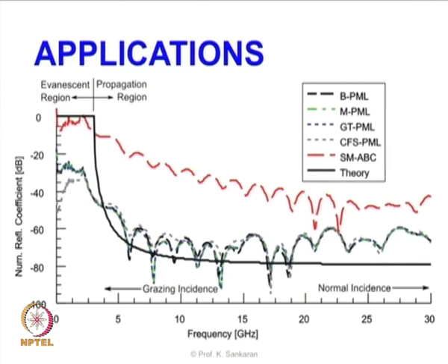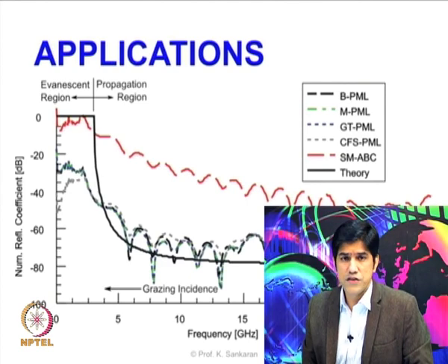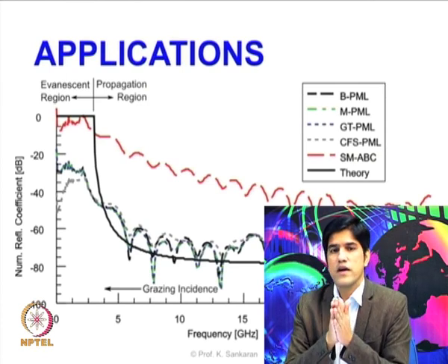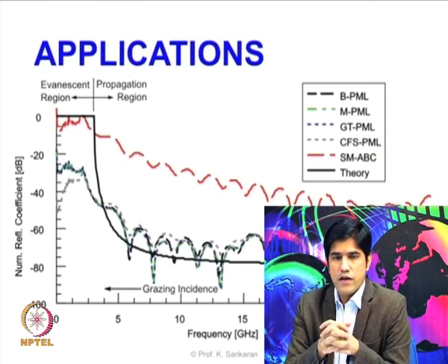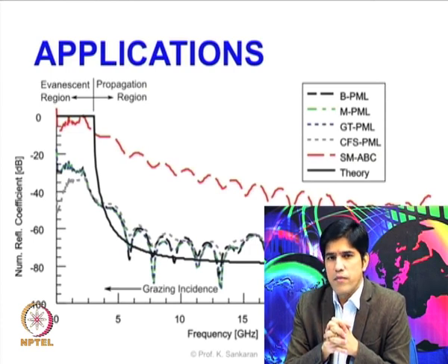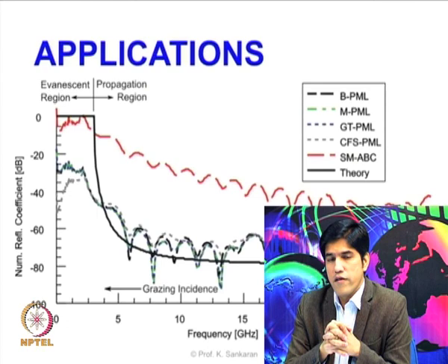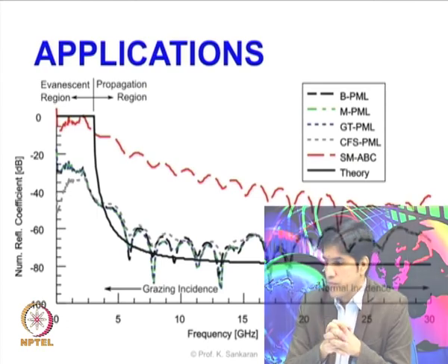So with this we are able to see a couple of important factors, and we will go into the next application. The factor number one is that the PML is working fine as expected, and we are able to see the trade-off that, as a scientist or an engineer, you have to make to ensure your computational cost versus accuracy is maintained. We can also see that for any plane wave or waveguide truncation, a lambda minimum as the thickness of the PML and roughly 10 to 15 cells is quite good, and this is what we have seen also in the example we have shown here.